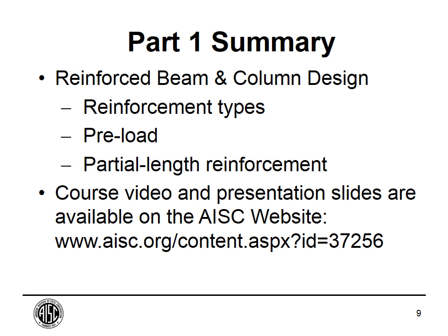Now, one thing I wanted to go ahead and define is what a preload is, because we're going to use that terminology in this presentation too. A preload is just a load that's on the beam or column at the time of reinforcement. It's on your structural member at the time when you add the reinforcement.